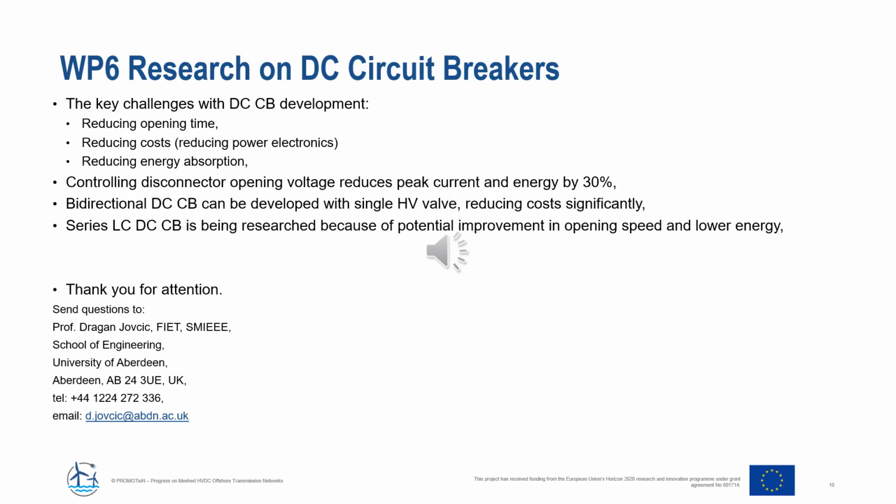Bidirectional DC circuit breaker can be developed with a single HV valve, thus reducing the cost significantly. And it is also shown that the new proposed topology with series LC DC circuit breaker potentially introduces significant improvement in the opening speed and the lowering energy.